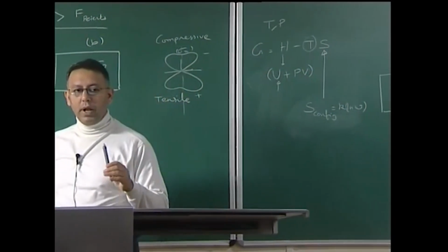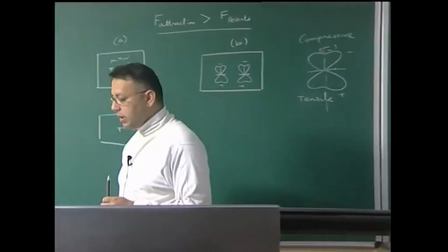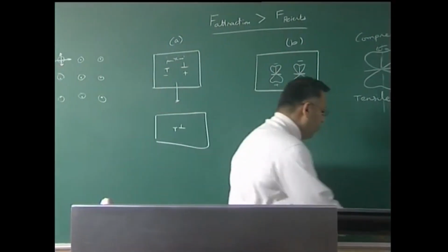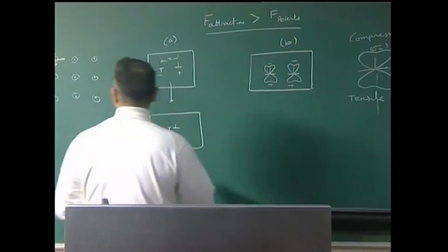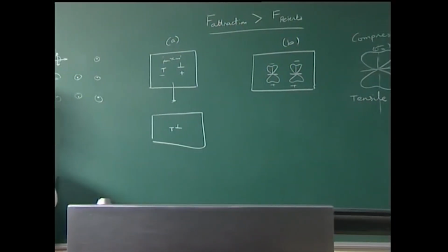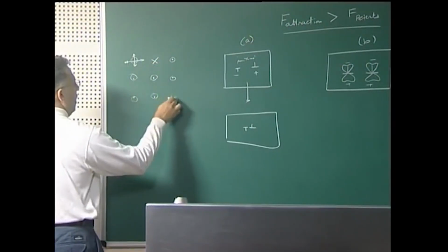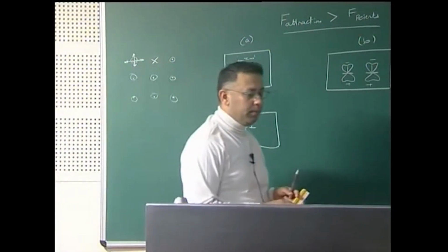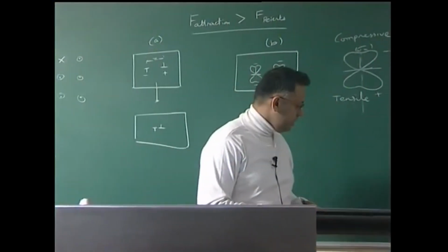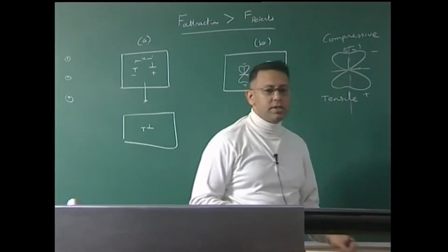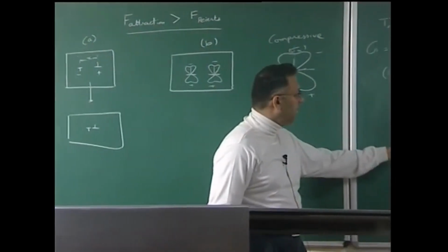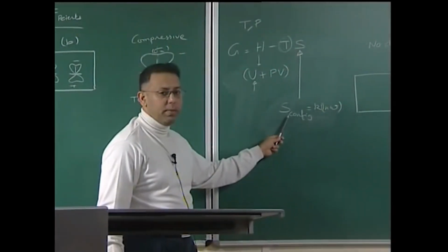Therefore, when I put a vacancy in a material, this vacancy could actually sit in one of the many lattice positions. For instance, if this is my vacancy, this vacancy could be present here, here, here, here, here, or in one of the many possible lattice positions, and this implies that this increases the configurational richness of the system, and that hence provides an entropy benefit.